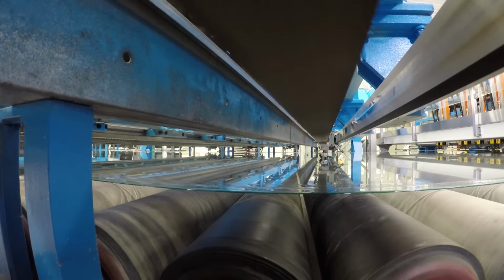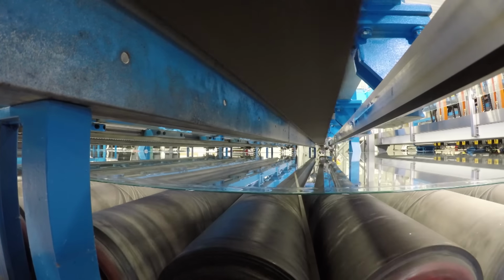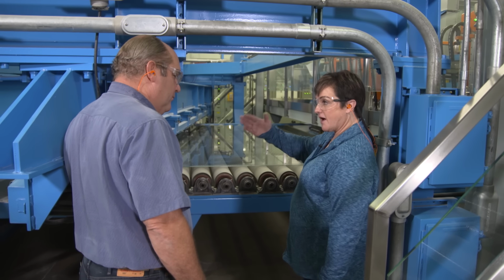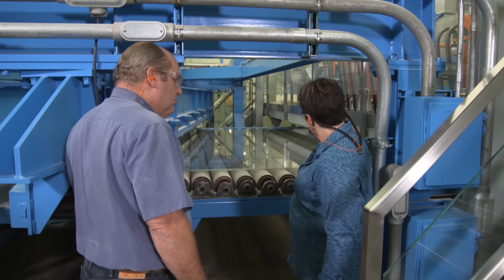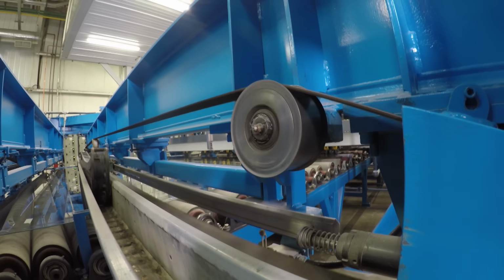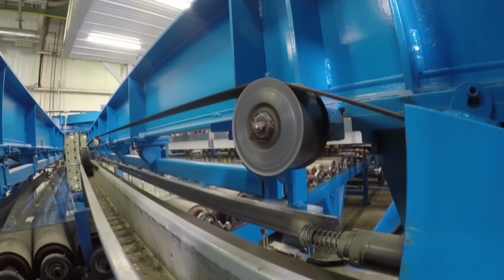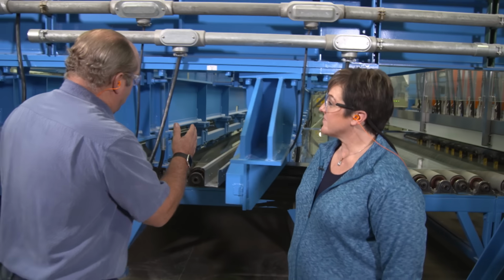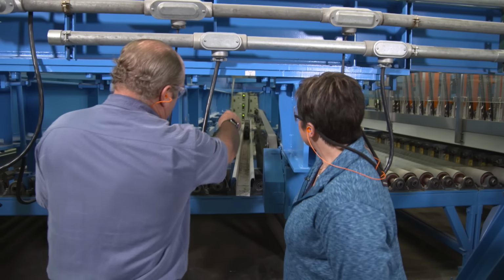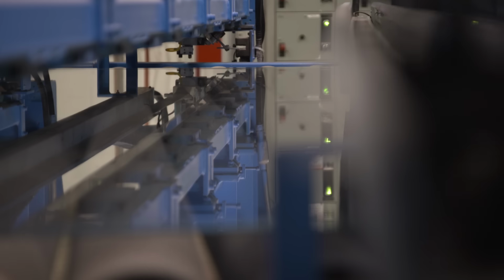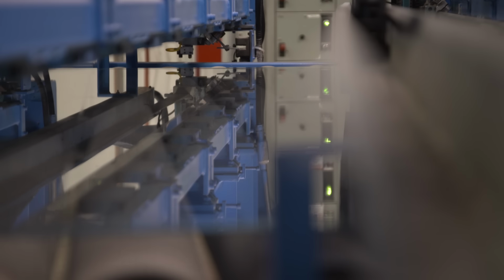The glass has now traveled 450 feet since it came off the tin. It's time to start scoring it. Okay. Making the cuts the long direction of that ribbon is fairly simple. Here we're making all of the cuts going across the glass. You can see it's at an angle. So that's not as easy, is it? Because this is moving. You put this thing at an angle, and it has to come back at the exact same speed as it's moving this way to make a perpendicular cut. Absolutely. That is so smart.